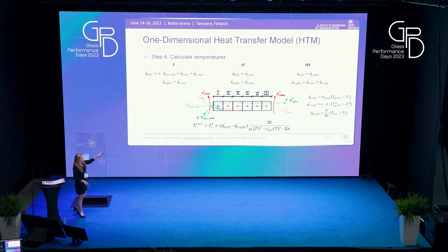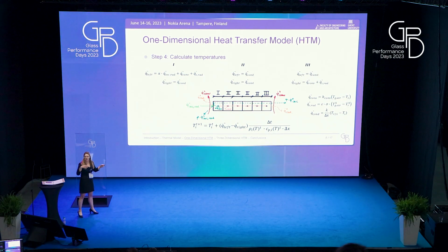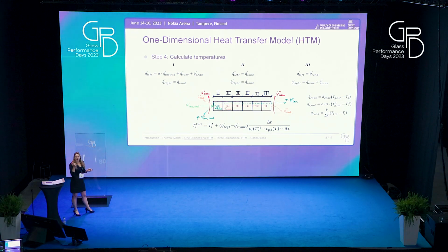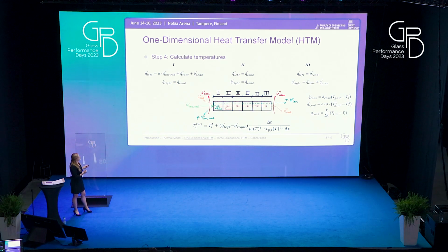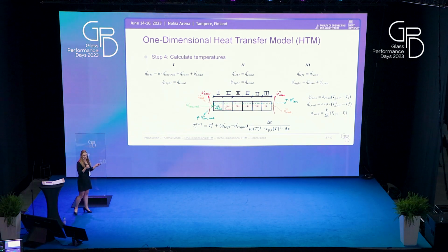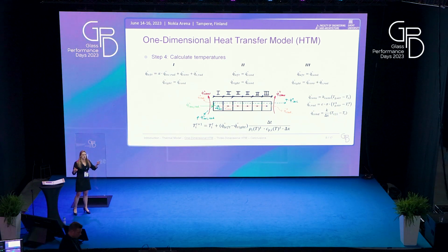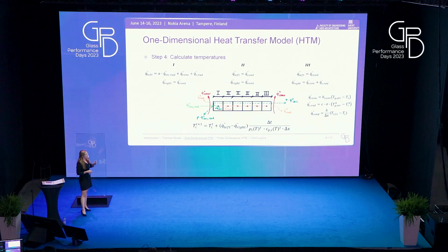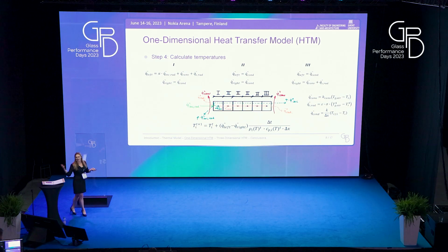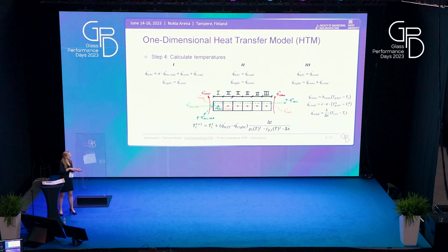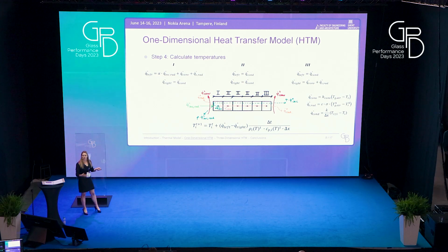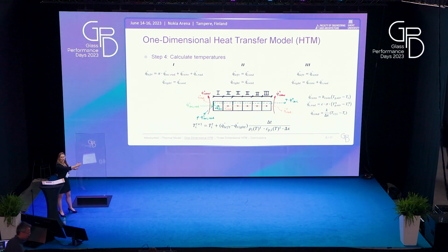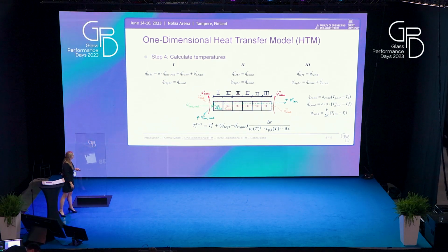With this figure, you can see that you have three different kinds of elements in your thickness. The first one is the one at the exposed side. What we basically do in this method is check the heat fluxes that come from the left, check the heat fluxes that come from the right, and balance everything out. The first element at the exposed side has from the left the influence of the absorbed incident radiation, the convection, and also the surface radiation. And from the right-hand side, you have the conduction of your neighboring slice on the right side.